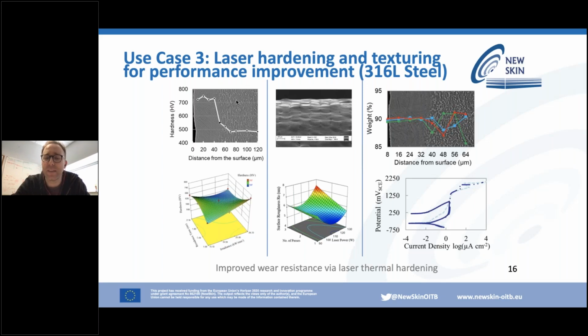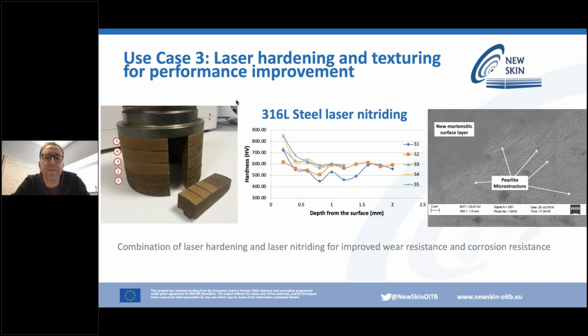It's very important in the automotive and in the mining sector, where we can produce very high depth, high wear resistance surfaces. While if we're working with smaller parts, we can dial this down, control it in a more precise manner to have micron layers, single micron layers of this hardened surface. We can also incorporate the use of process gas with this for, say, nitrogen incorporating for nitriding as well. This can be, again, done as a first step in a process to then incorporate the laser texturing on the nitrided surface as well.